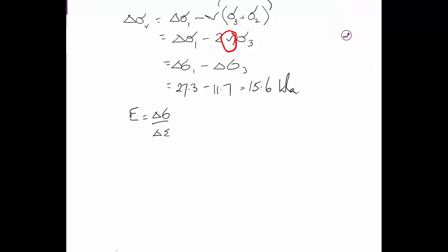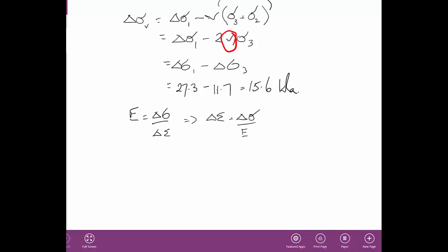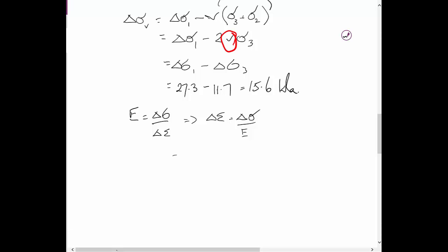Change in strain equals change in stress on the elastic modulus, which equals 15.6 that we just calculated, divided by the modulus, which was 12,000 given before.